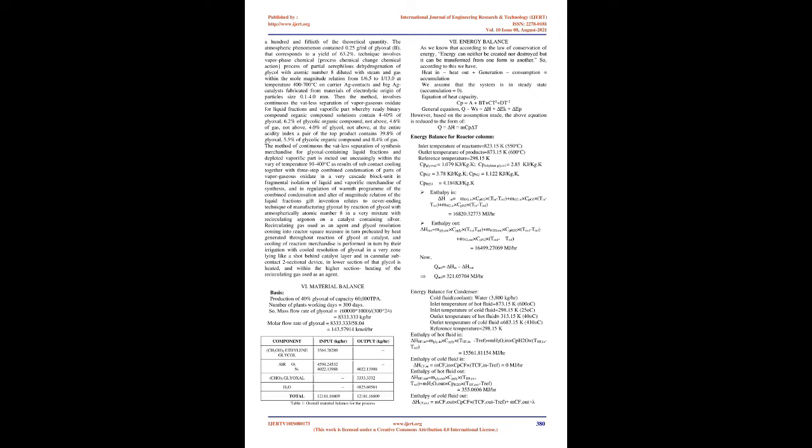The air was passed at a rate of 180 liters/h. Oxygen was therefore taken in 150% of the theoretical amount. The condensate contains 0.25 g/ml of glyoxal, which corresponds to a yield of 63.2%. Process selection. Of all the feasible processes available for the manufacture of glyoxal, the oxidative dehydrogenation using silver catalyst method is selected. The process selection criteria are: glyoxal was obtained by the oxidative dehydrogenation of glycol.